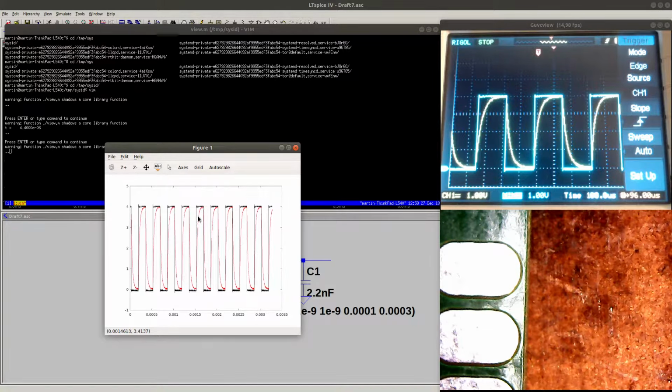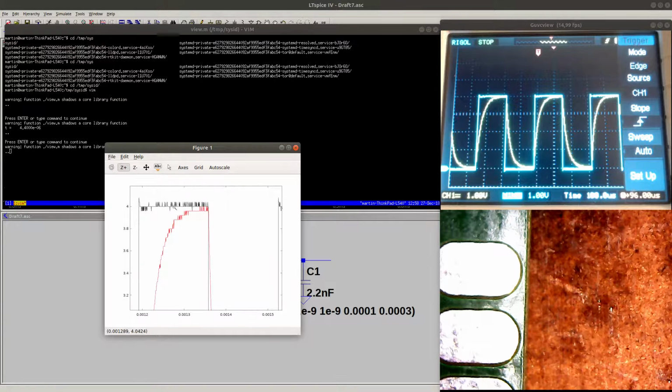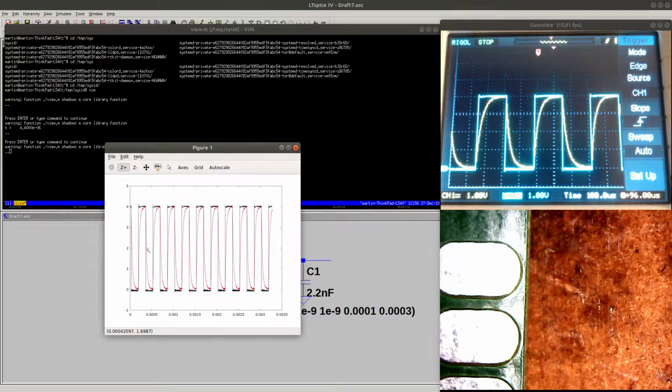So if we know the transfer function, we should be able to simulate the system and get a very similar response as the actual measured response here. And this is discrete measurements. So you can see there is some noise there, and there is a certain dt value between the measurements. And also they are not aligned. So before we can do system identification, we need to align these waveforms so that they align more perfectly.